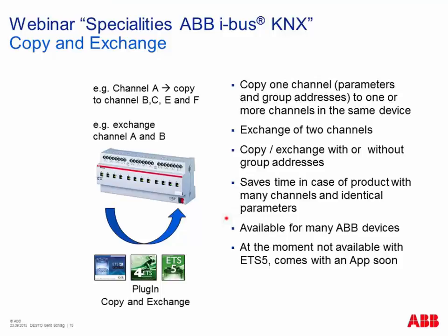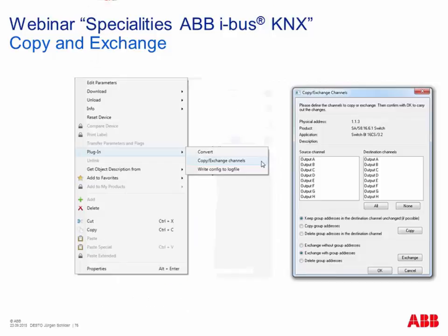Another nice feature is to copy and exchange the channel of a device. I think it is very nice when we have devices like our switch actuator with 12 channels. So we can do the settings for one channel, channel A for example, and then right mouse click in the ETS and copy the settings with or without group addresses to the other channels. Like for example here, you click here on the device, right mouse click, plug-in, copy and exchange, and then